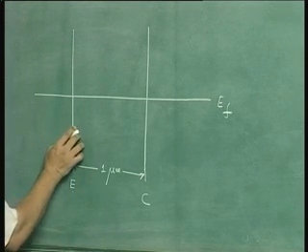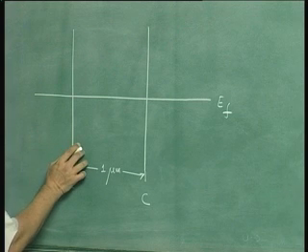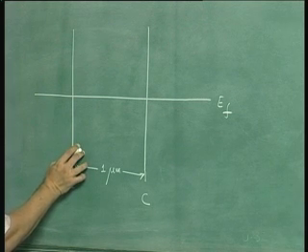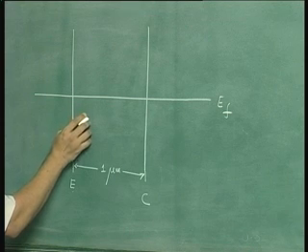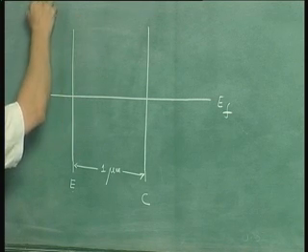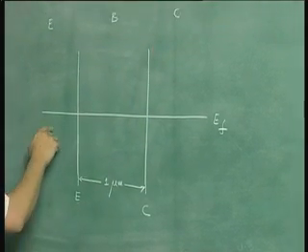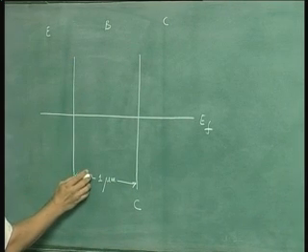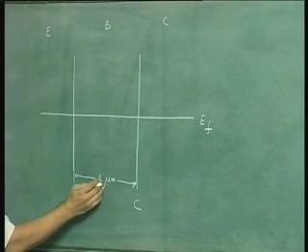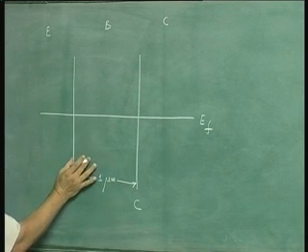When both emitter base junction and collector base junction are zero biased, then you recall that the depletion width here was 0.32 microns, out of which 0.29 microns was on the base side. So this is emitter, this is base, and this is collector. So 0.29 microns on this side is somewhere around little less than 1/3 of this distance. So we must draw the diagrams to scale.